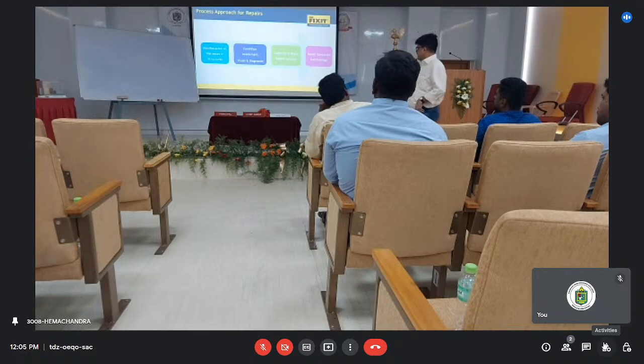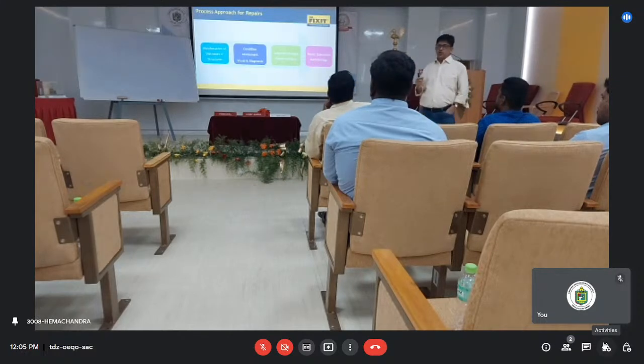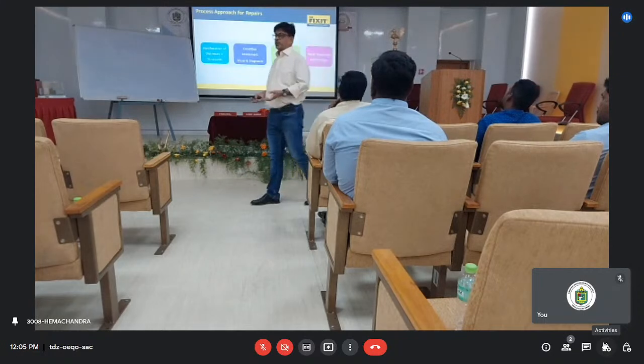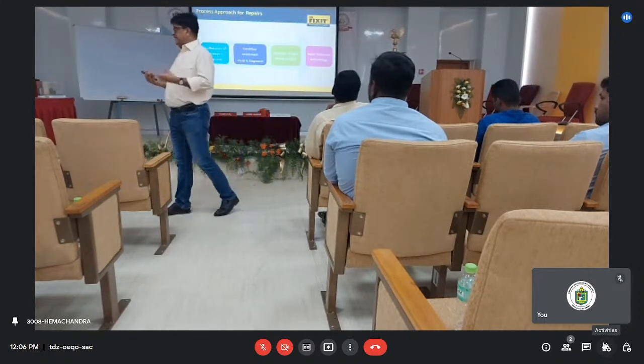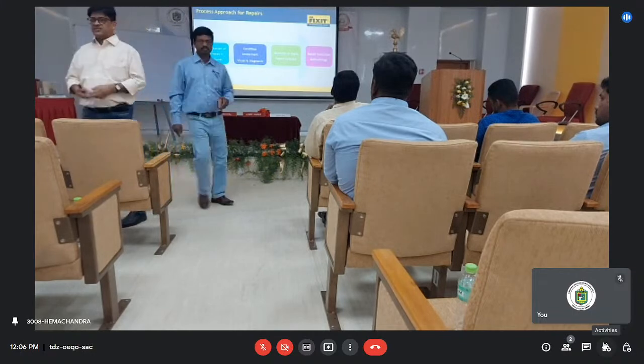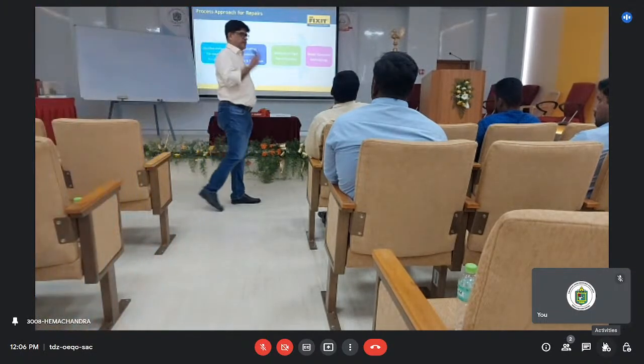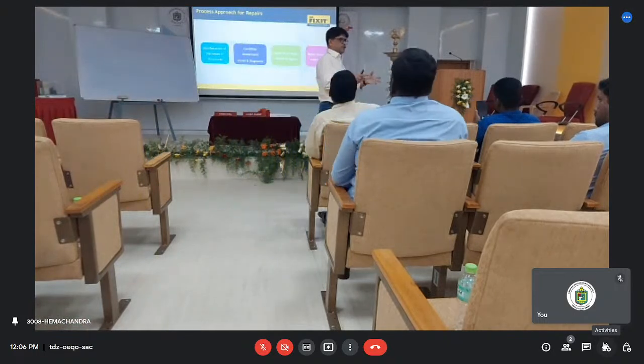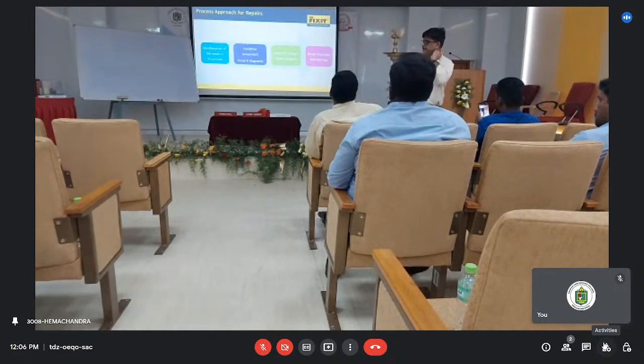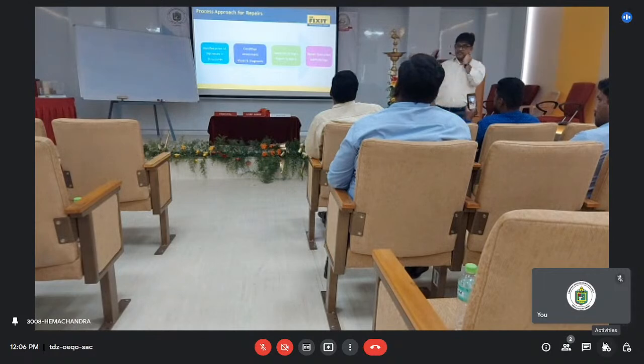That's the first thing. Second, for the RCA, I have to know what condition assessment processes I have to do, how I should check it, what areas, what processes. There are several kinds of processes: visual observation, destructive test, non-destructive test, but I should understand what to do, where to do what. Then selection of the right repair system.